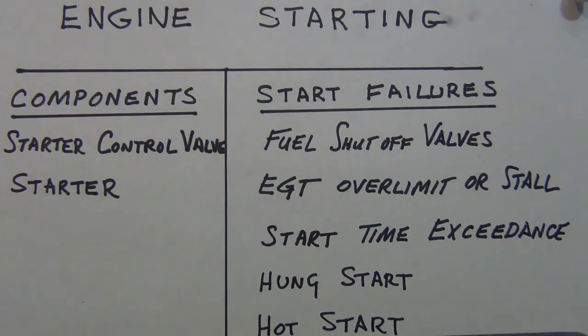All right. Now, just to understand a little bit about the process here. On the wet crank, you're going to have the master control switch on the on, and that's going to be on between 15 and 20% of N2. Then after you have a wet crank of 15 seconds, when the master control switch is set to off, then the fuel's cut off. Obviously, when you have the master control switch off, then the fuel shut off valves are going to be closed, and that fuel's going to be cut off. Okay, and then there's going to be a resetting of the ECU.